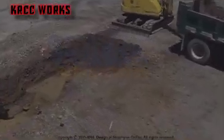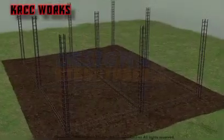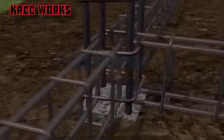Beam reinforcement shall be as per drawings. Top bars, bottom bars and stirrups to be placed with proper development length.